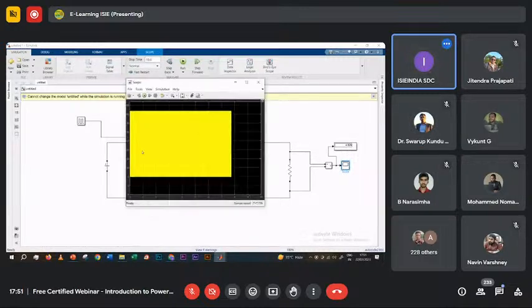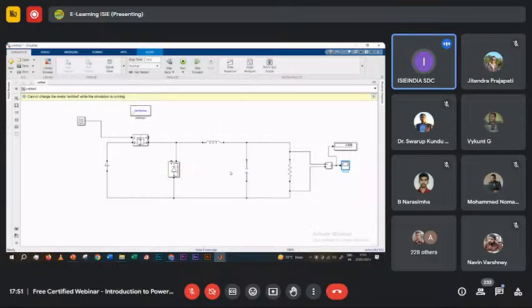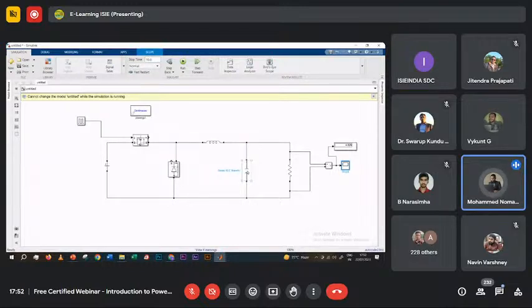I think it is not showing the minus, it is actually showing the output DC itself, but there is a huge ripple here. So I need to check the value of this capacitor. Is the direction of diode correct? So diode is correct, sir. Diode is unidirectional.